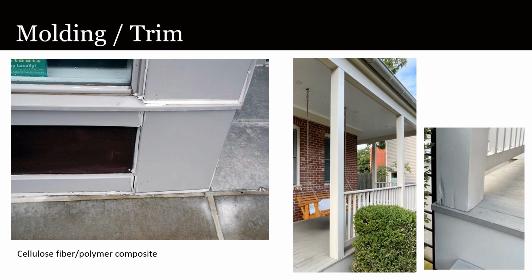Previous versions of this composite material have not always performed very well, so using material from a reputable manufacturer would be advised, and most importantly, following the manufacturer's advice about finishing and fastening. The need to coat cut ends before assembly was not understood in the otherwise successful use of the material for the porch post illustrated on the right, where one can see evidence of failure already emerging at the base of this column in the little inset there. This is damage one might have expected at the base of even a wood column that was similarly installed without sealing or painting its end.